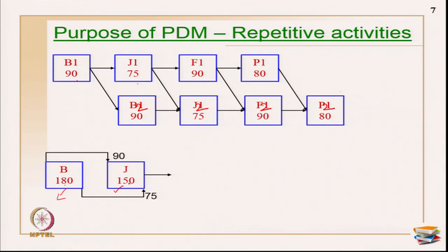So, how do I now fix the relationships? All these relationships I have, how do I fix them? What I am going to do is, after the brickwork started, 90 days after the brickwork, joinery should start. So, this will cover my brickwork. After the brickwork, this logic is primarily covered. After the brickwork, 90 days later, brickwork takes generally 90 days, then the joinery starts, and this duration is given here with the lag.